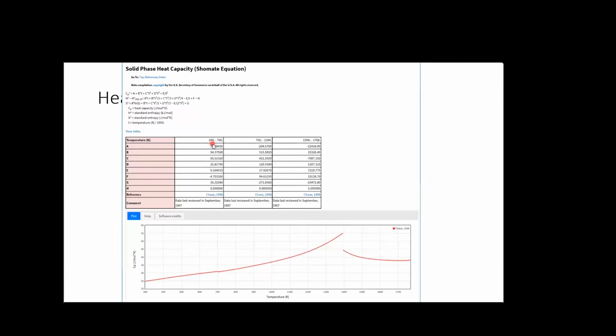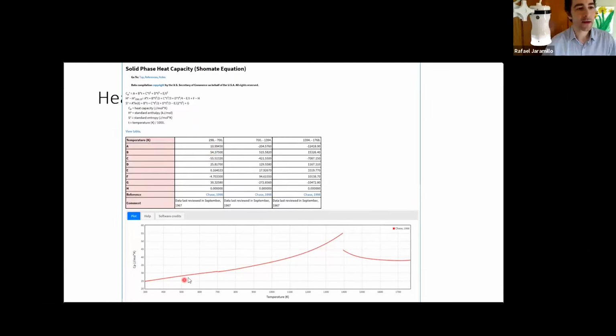Is it because of the different phases? Because of the different phases. The different phases have different heat capacities. In general, different phases have different heat capacities. Right. So you see this is the non-magnetic HCP. And then there's a little jump in the heat capacity. It jumps to a slightly lower value. And you enter the FCC magnetic phase.